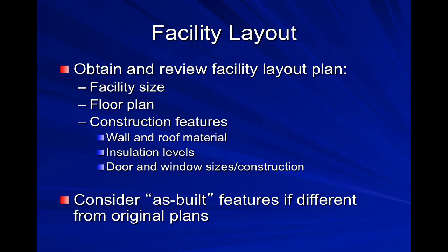The facility itself. Not only do we need the square footage of the floor, but we also need to know how big the walls are and the roofs and the windows, and other things to consider might be the directions that they're facing. Are they facing south or north or west? Are there other things to consider, such as prevailing winds that are coming in the large exposed direction of the facility? The original plans that you have may be obsolete, so those might need to be modified or look for replacements.